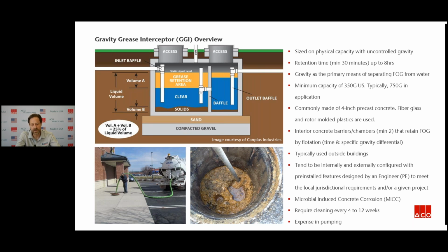And I think one of the things to remember here is that this is not necessarily separating grease out. It's containing it. What you will still have to do is have some kind of pumping facility or a pump truck come and suck all of this out to take away to be further processed. It works on settling time. To maintain these and keep up with them, you've got to understand how much grease is entering the system. That can be a nuance. It can be tricky, right? So there are certainly things to think about.